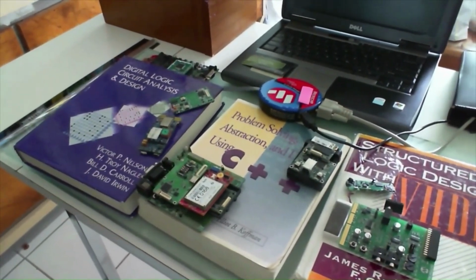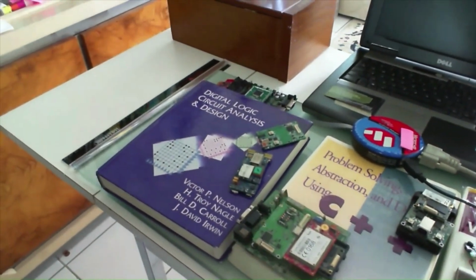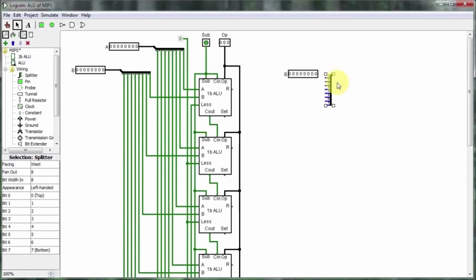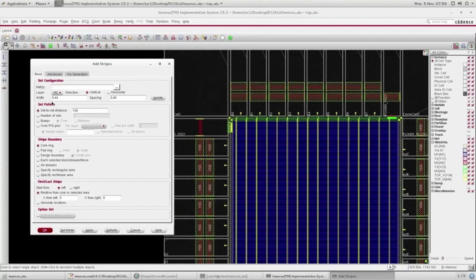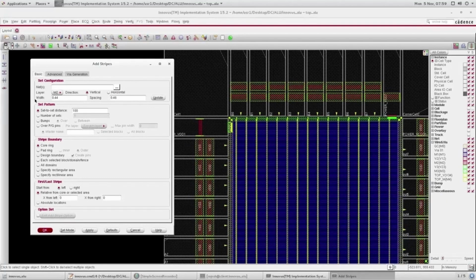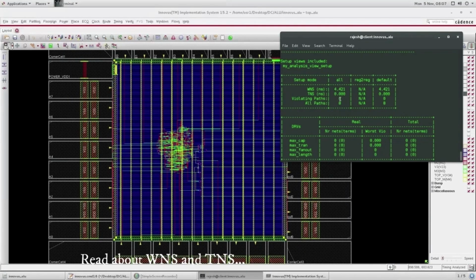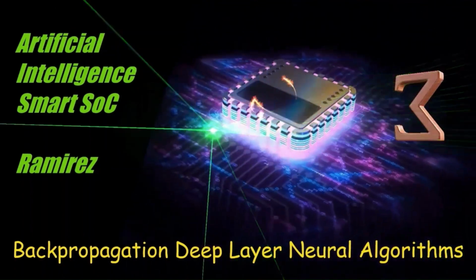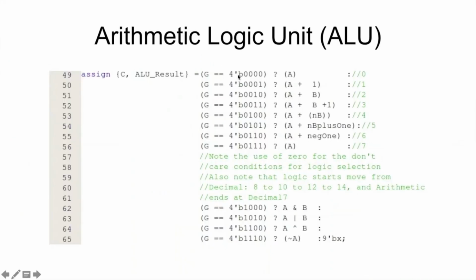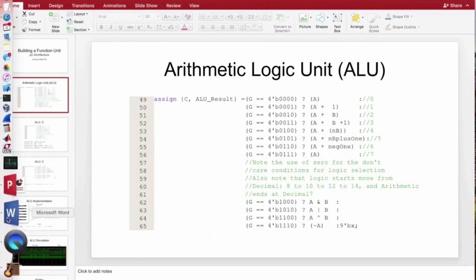So placement is often run before the logic has been finalized to obtain an early indication of the timing and wireability. At this point, the feedback may be used to influence the logic changes. This may also be the time at which the locations of large objects are determined. The placement program may run more quickly by not considering such details as legality, and there may be less emphasis on achieving the best possible results.